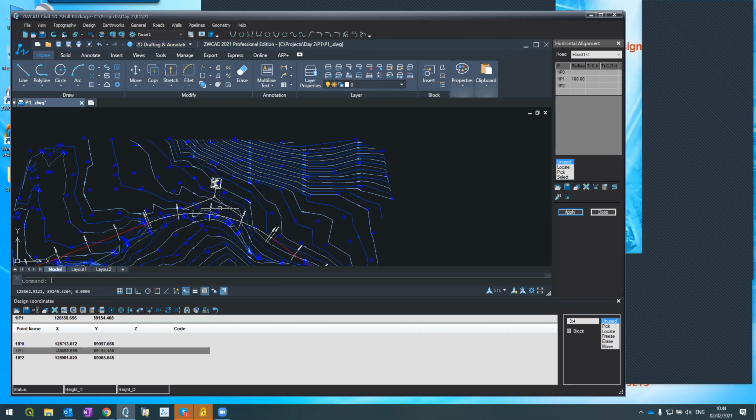If I want to create defaults, I change it in the prototype. In this case, my prototype was white. But if you go to prototype, you do File, Open Prototype. And then in the drawing, there's a file name there, prototype underscore DWG. You change the colors there. Whenever you create a new project, the system will inherit the colors from prototype.